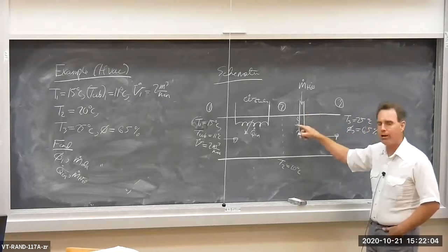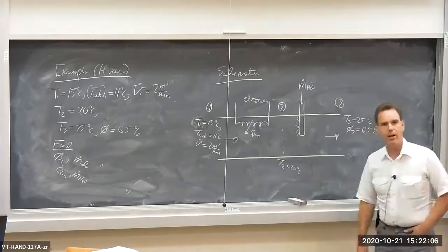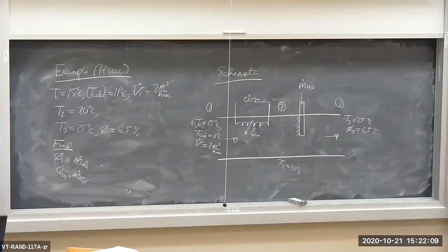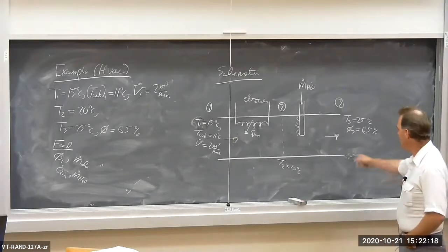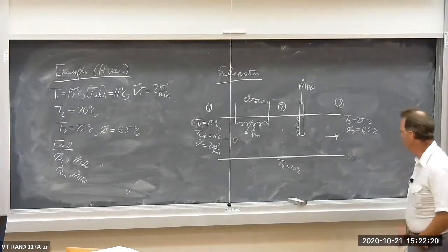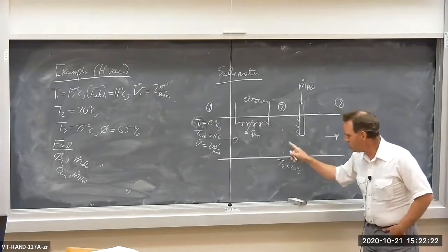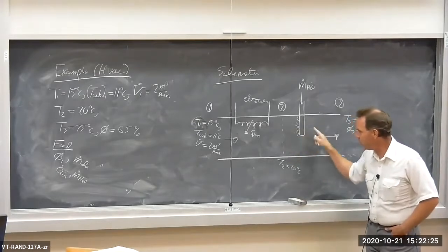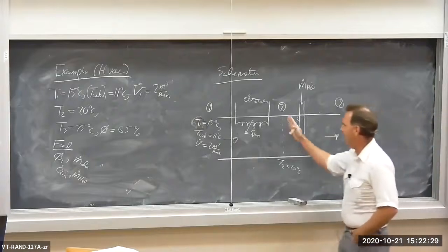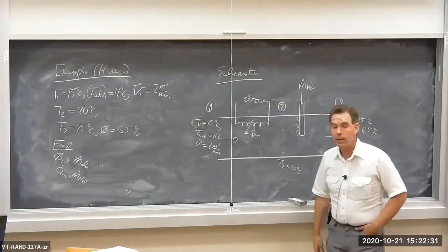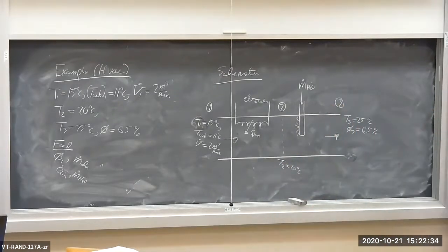So we have a little sprayer here. You can see that we're spraying little droplets of water into the duct, and that's vaporizing and increasing the vapor content of H2O in the air. The temperature just before we get to the humidification with the injection of H2O, the temperature right here after the heating at location 2, is measured at 20 degrees C. Then we add H2O.